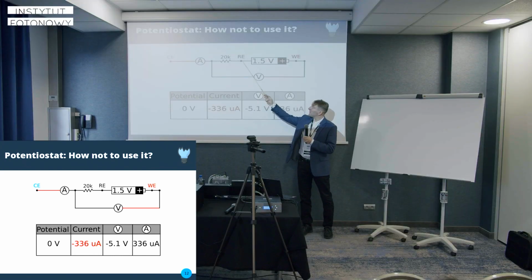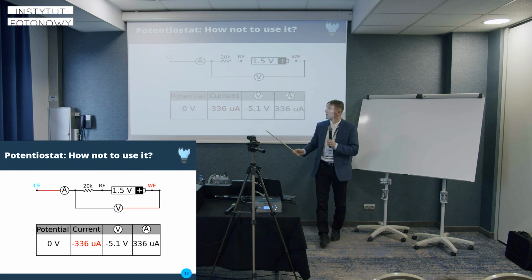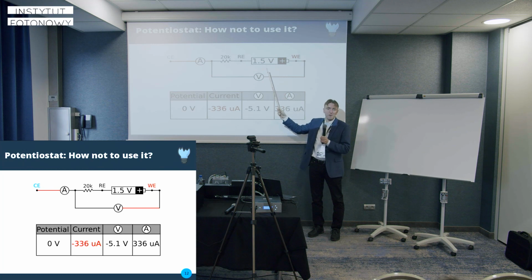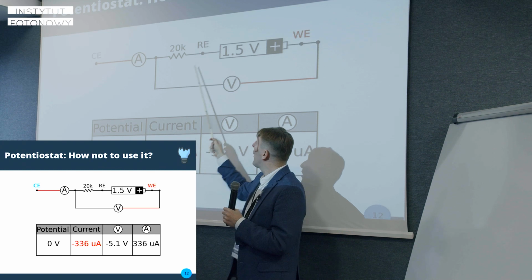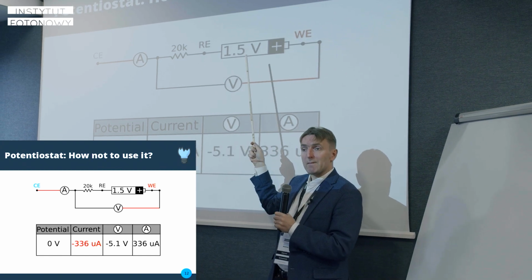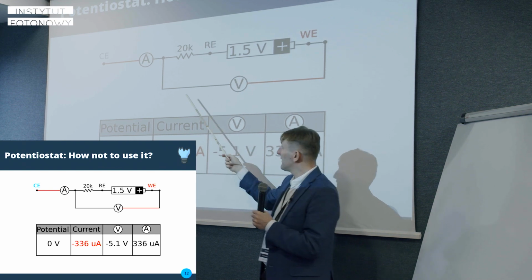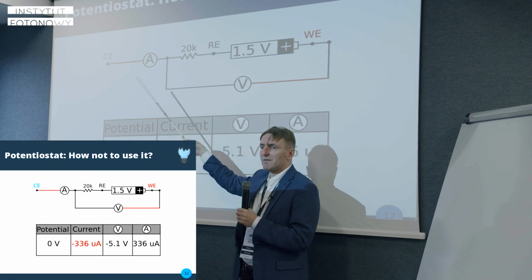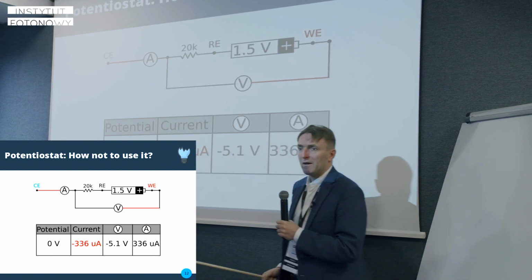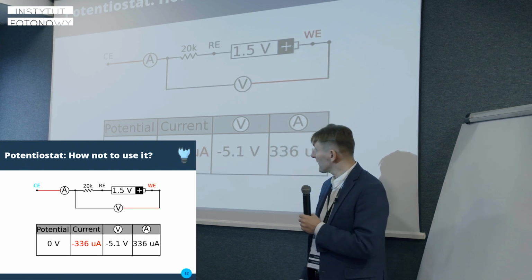Now we would like to keep up the voltage set in the potentiostat between this point and this point. So that means that we will have to somehow lose the difference between this voltage and the setting on the internal resistance of the battery alone. This guy doesn't play a role here anymore. It just limits the overall current, but it doesn't help us do a thing here.